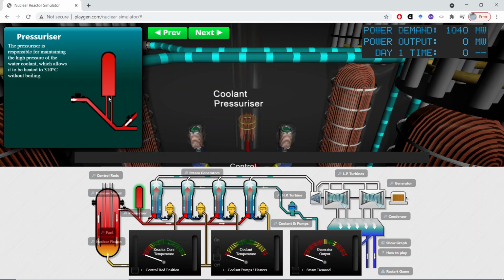So there is a pressurizer which is a volume attached to the primary circuit, and actually it has a shower inside, which operators can control, like opening or closing a valve. You can imagine that the pressurizer is full of water until maybe 1/3 here. So here you have water, in the upper part you have air or nitrogen or water steam, because this water is hot.